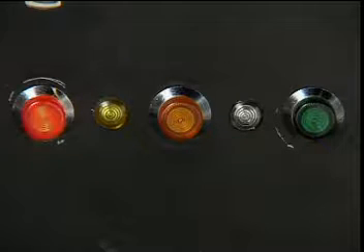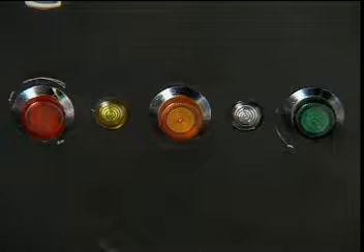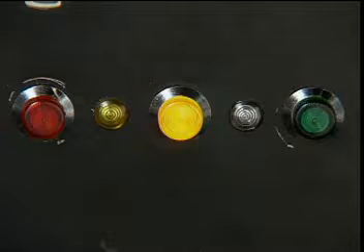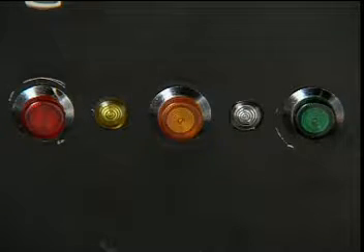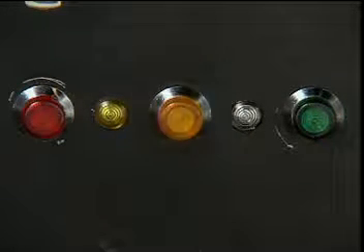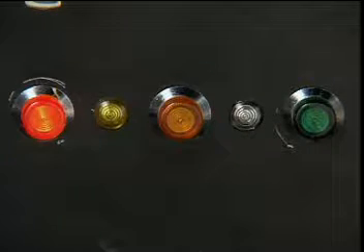After completing all of the active Quantum faults, the sense faults flash out on the yellow warning lamp. When all of the faults have been displayed, there will be a 3-second delay, after which the flash-out sequence begins again with the first active Quantum fault code.